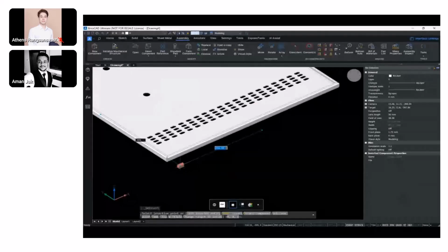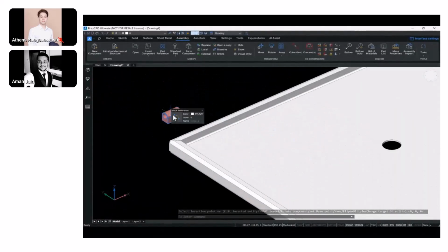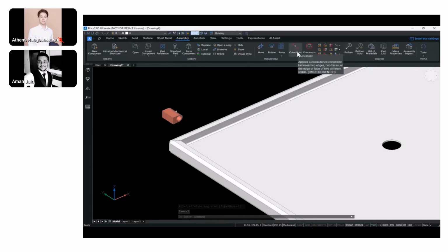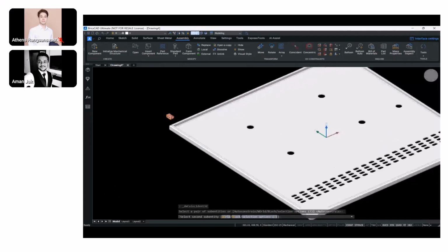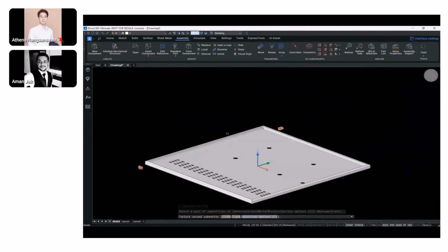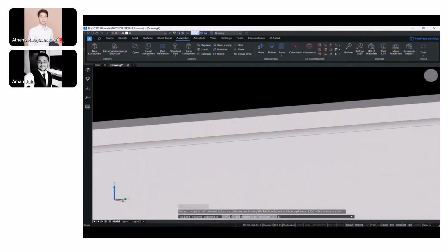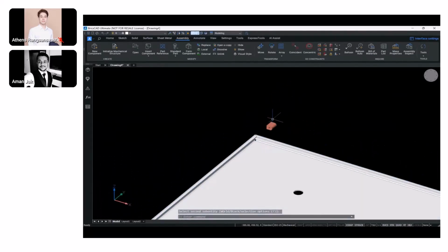There are 2 hinges. And we'll see how we can use BricsCAD's constraints, the 3D constraints, for us to be able to position it on its actual place, right? So we need to be able to constrain it on the side of the door. First of all, we'll make it constraint ready, so that for the software it really becomes easier when we apply constraints to move or rotate the body. So I'm selecting this face and I'm using a coincident constraint, which will make these planes coincident with one another. I can use the same constraint once again for the top face of the hinge and the bottom face of the door body, where this hinge is going to be placed. Right. So that constrains it completely in terms of the position that I want to place my hinge in.